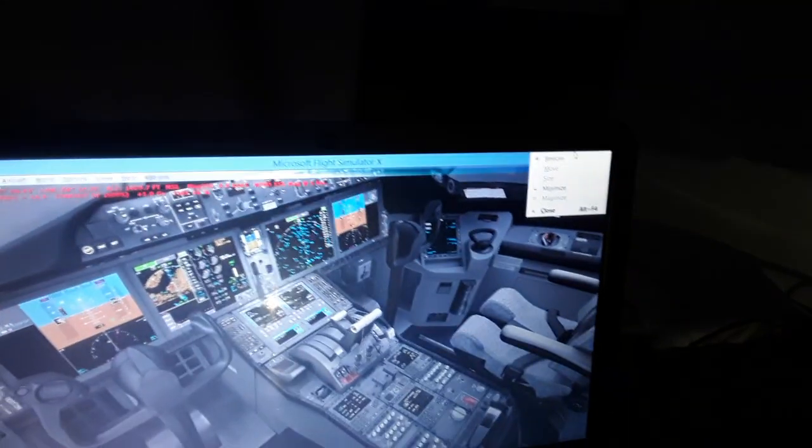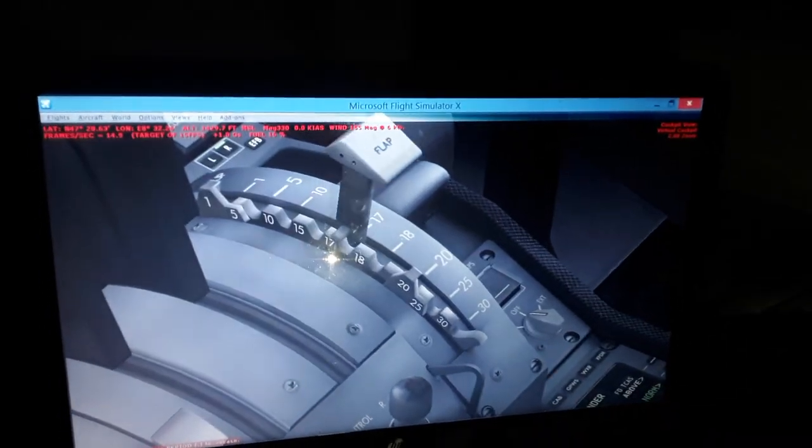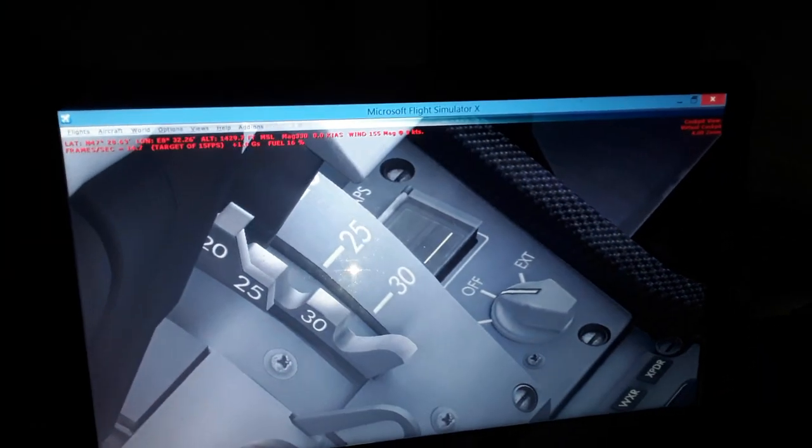You're going to see many interesting things. You can see the thrust lever positions. We have the autothrottle over here, and the thrust reverse for the engines. Over here, pull back, is the autothrottle disengage switch and the takeoff go-around switch. Also the speed brakes over here, and we extend and retract the flaps. We can set the flaps the way we want when we fly, before takeoff, before landing, however many degrees we need. As you can see now they're fully extended.